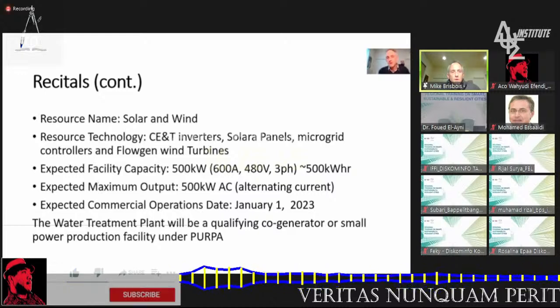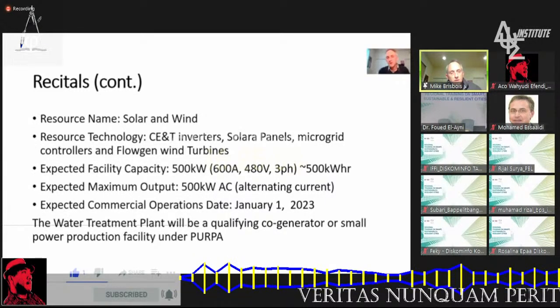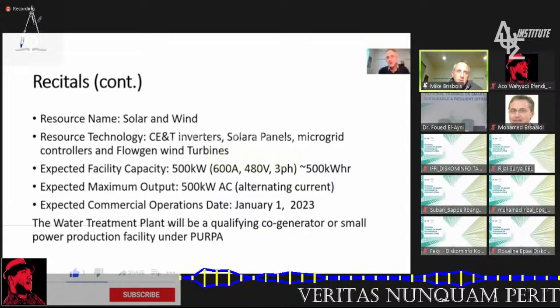Okay, so in the particular case we're showing here, they had solar and wind. We actually had a company doing the inverters and the microgrid controllers. So if the utility cuts power, does it switch over? Does it stay on the common coupling bus? Does it stay energized on both sides? How does that work? Do they push energy back to the grid? Do we use it internally? So there are a lot of questions for the controller to figure out to make these operational.